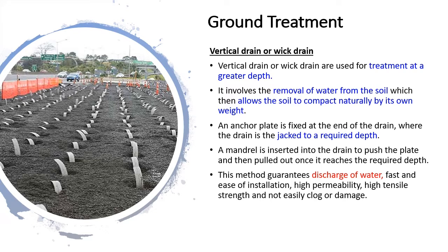The proprietary system, consisting of sand-filled geofabric tubes which can be lowered into small diameter pre-filled holes, is marketed for this purpose and has the advantage that the strength of the fabric helps prevent the drains being severed by small downslope movements.